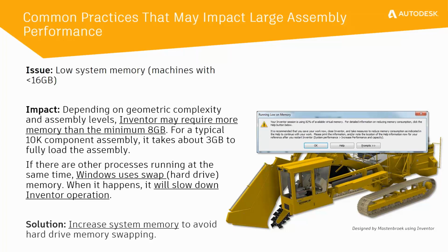The obvious way of resolving this is to simply increase your system memory. The alternative is to reduce how much memory you're actually using, either inside of Inventor or through other background programs that might be stopping you from using the available RAM that you have inside your system. And we'll talk a little bit about that later.